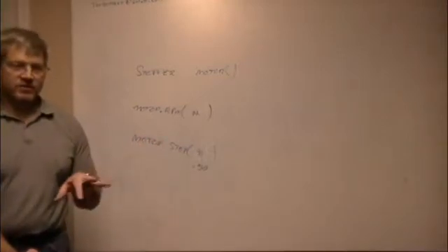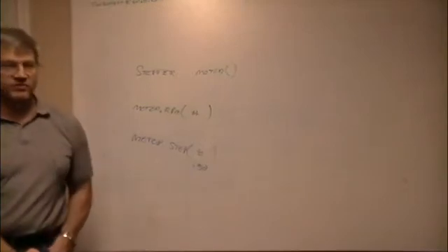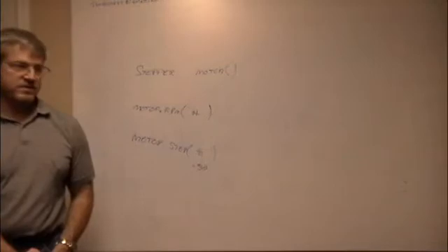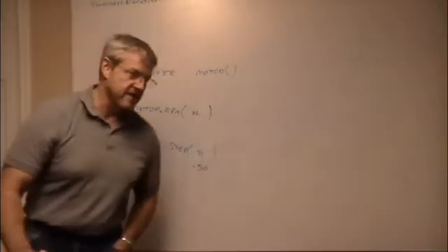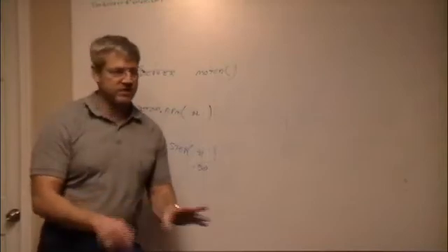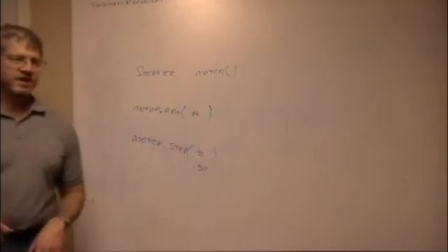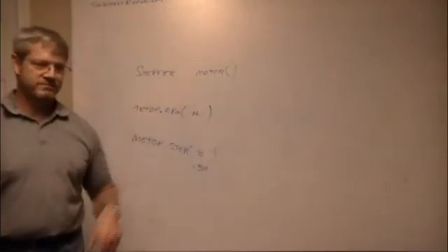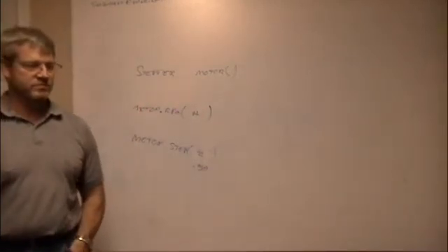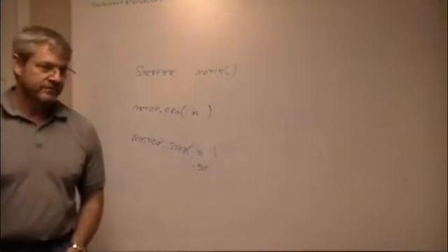And the minimum speeds, because you're driving it off of that timer, right? Well, actually I was not driving it off of that timer. I was using direct digital writes. So that just means the time it took me to go into that function, go through the if-thens to get there, fiddle those bits the right way, and then pop back out and be ready to do it again. I couldn't do 2,048 times 1.8 times per second; that is about as fast as I could go on that guy.